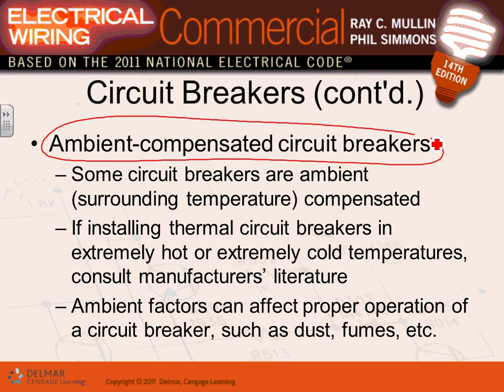If your circuit breaker is in a very cold location like Minnesota, where it was 6 this morning, you put a circuit breaker out there, do you think it's going to wake up if you have an overload condition? That guy's going to be so cold. It takes a lot of overload condition to get that one to wake up. So you will have to take this into consideration. The ambient temperature effect on circuit breakers is major.